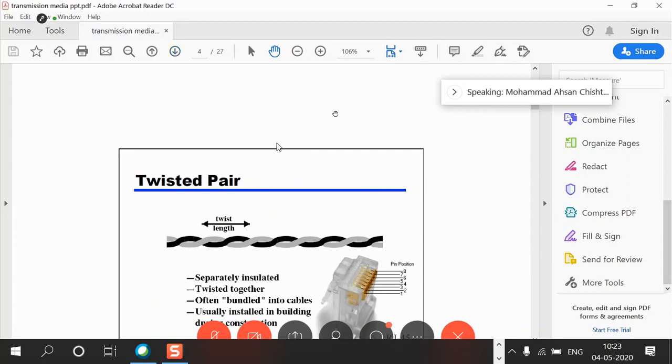As is visible here within this picture, twisted pair is one of the oldest and still commonly used communication mechanisms. Have you seen this? I think most of you would have seen it. Your telephone line is a single twisted pair cable, in which there are two lines. You can see one black and one white. One of the lines is used for signal. Another is for ground reference. The receiver uses the difference between the two signals to find out the signal that is being transmitted.